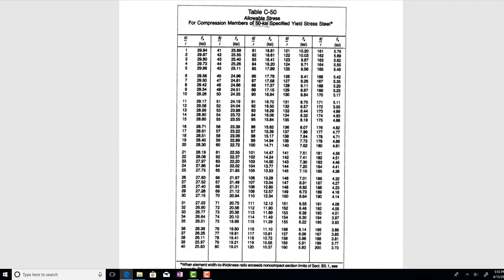All right, column stability factor. Column stability factor, if you recall, is simply a function of calculating KL over R. K was the adjustment for the end connections. K is typically 1.0 if we're pinned. There are some other values that show up if we're not pinned.